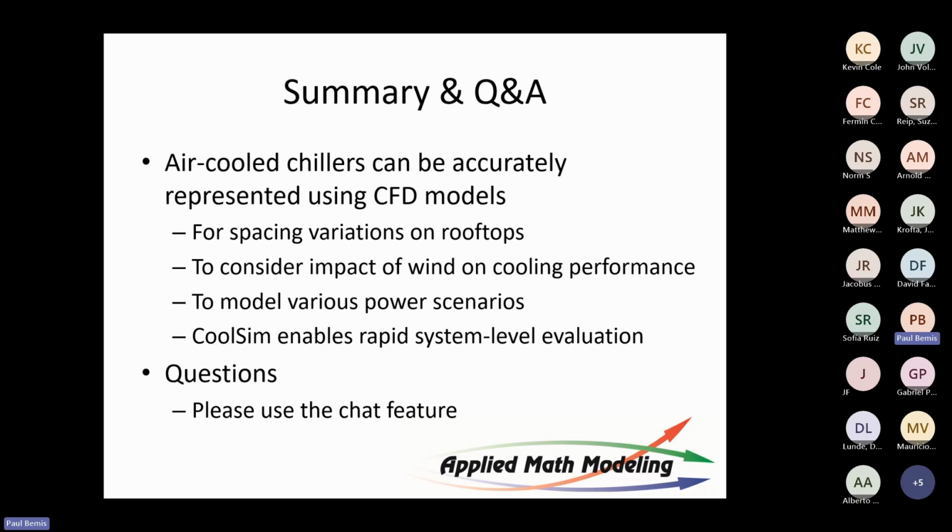But this kind of work is becoming more important. We have gotten pretty good at getting the heat out of the room. For the past 10 or 15 years, it's been about how we model the interior. And that's pretty well understood: how to optimize the separation of hot and cold using containment, fan walls, high density environments. We know just about how much you can get in terms of air. Liquid now as well, getting more.